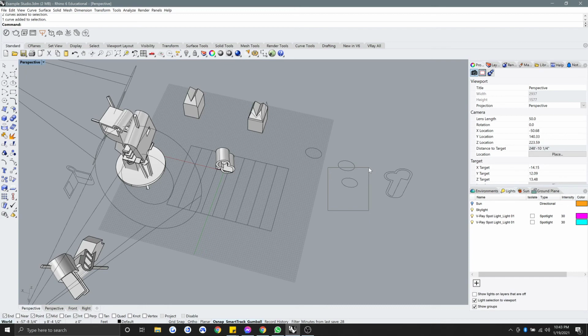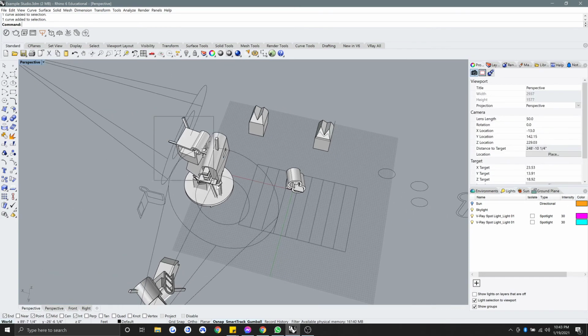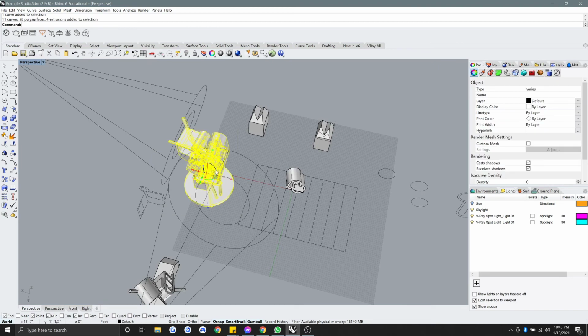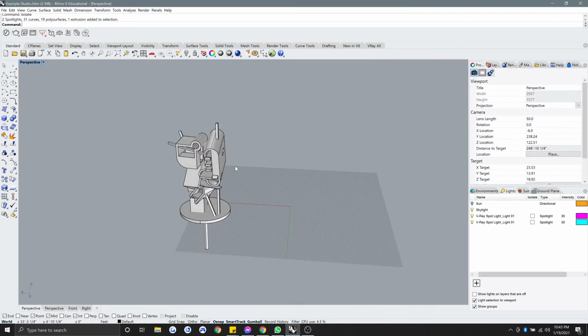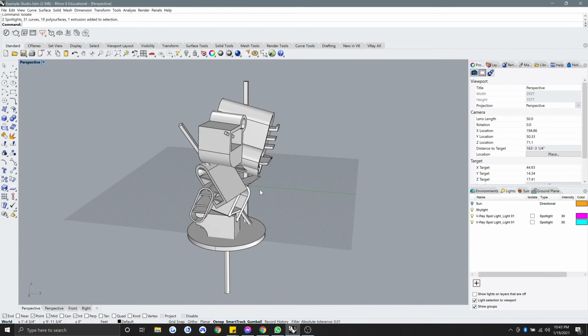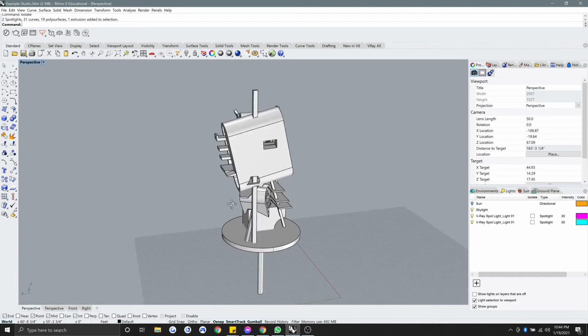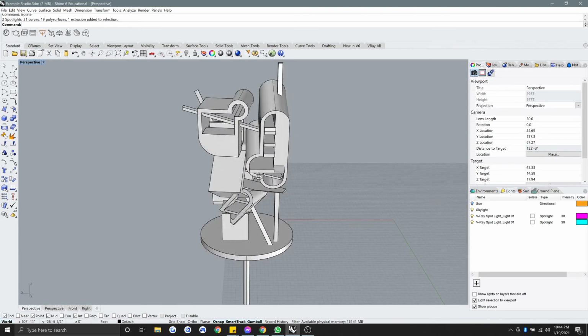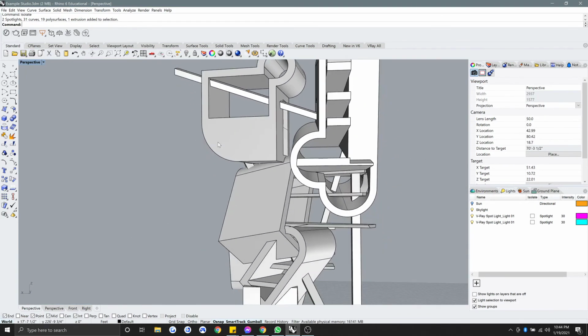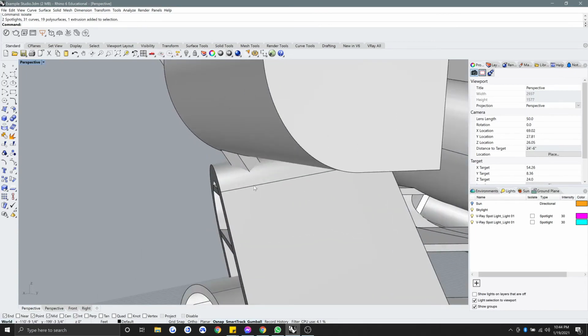So you see I'm touching that circle, but I'm only going to select this interior circle. So what I'm doing here is I'm just selecting down and to the left to get only this thing, typing isolate, so that it's the only thing left. And then this is the model I'll use to show you all how to do your turntable rotations in the upcoming, very upcoming video. It will be produced momentarily as soon as I'm done recording this one. I just found another sloppy moment.